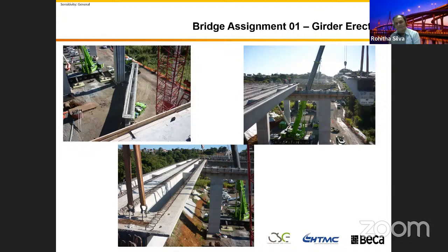If someone wants to do that, I can give you a design to fit in that one. It's difficult, a little bit expensive as well, because over here we use a 6 millimeter thick plate and bend that one to get that shape, and they screw that one into the face of the abutment.